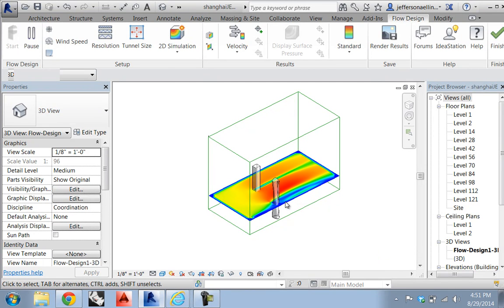So, I probably went a little bit too small because the edge of the box is obviously interfering with the flow around this building now. So I'm not getting an accurate result because of that. Out here, you can kind of see that the flow breaks to something a little bit more consistent, but again, I don't know how it's reading this geometry. It doesn't look like it's reading it properly. So this bounding box is a little bit small for what I'm trying to test, so I'm going to slide that back out. Hopefully, wrong one. Just to enclose a little bit more area.